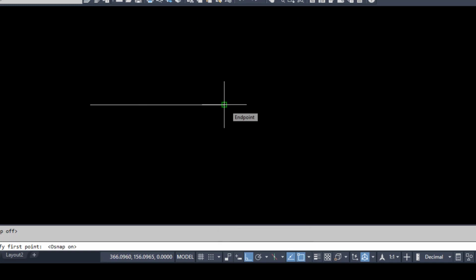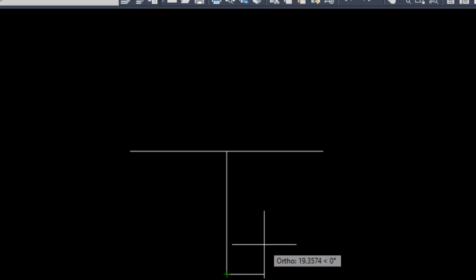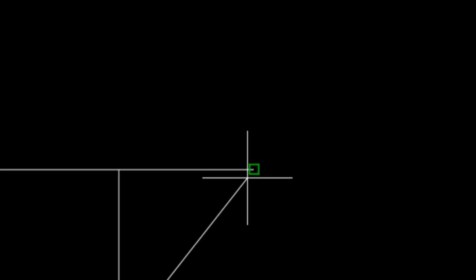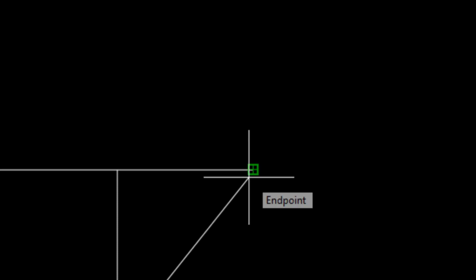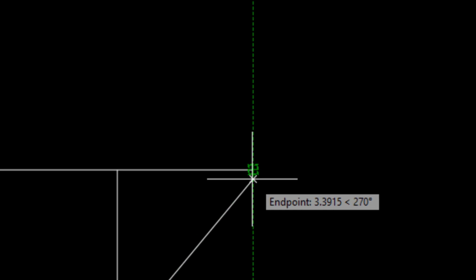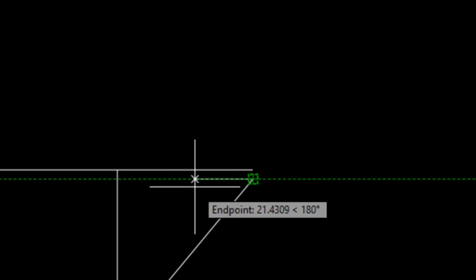Now, it will highlight the endpoint, and it will also highlight the midpoint. So suppose I want to start from the midpoint and I directly click on the next point here. As I go near the endpoint, it will show me the preview. I need not go beyond this point, and I will do a left click directly. As I left click, you can see that it goes directly to that endpoint. Also, if I click somewhere here, I can make it directly over here and click on the endpoint again over here.